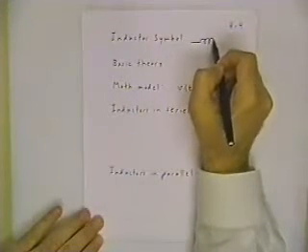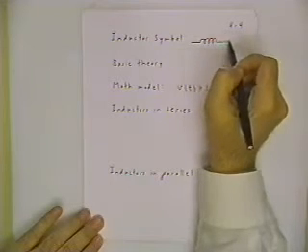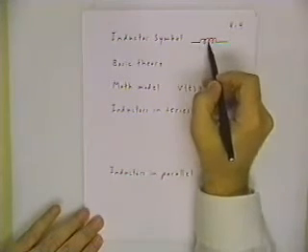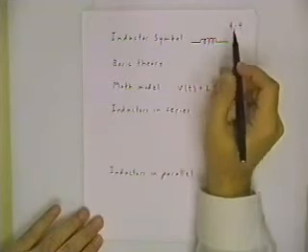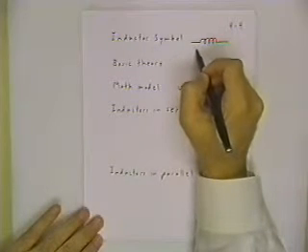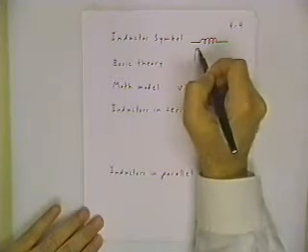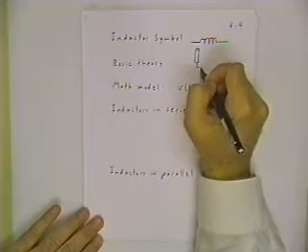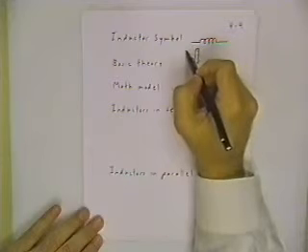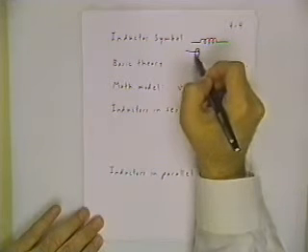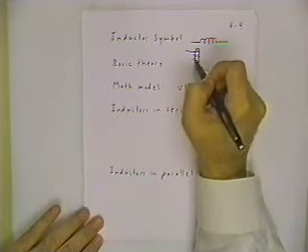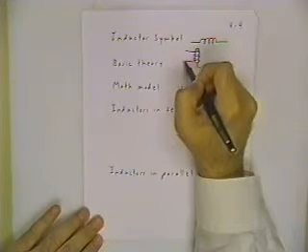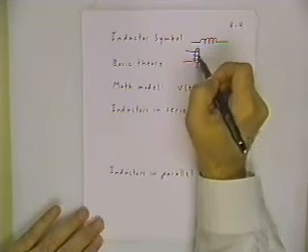It also turns out to be a fairly good schematic of how an inductor is formed. You just take a conducting wire and make a bunch of turns in it. For a practical inductor, usually you put some kind of ferromagnetic or iron core, and you let the windings come in like this, and that gives you a much stronger magnetic field inside here.